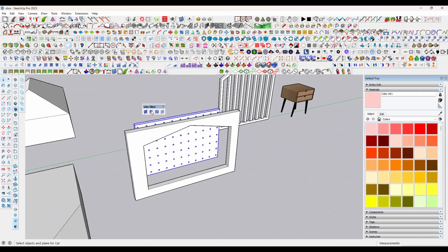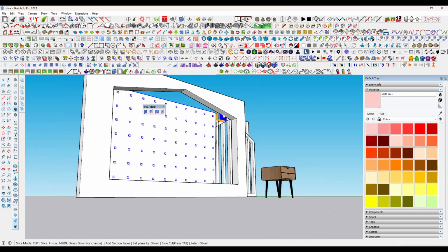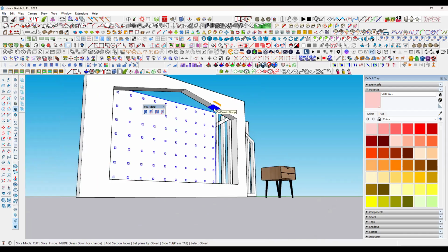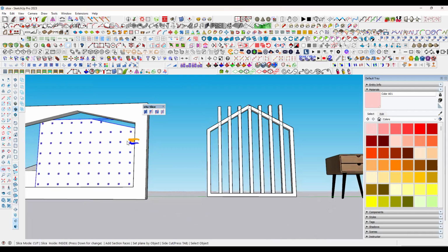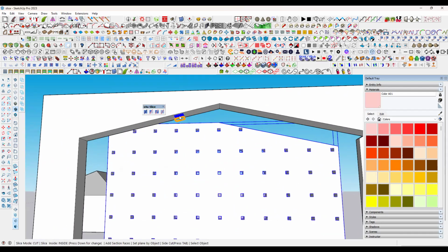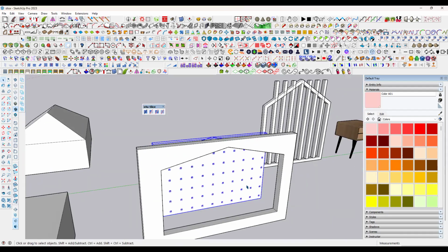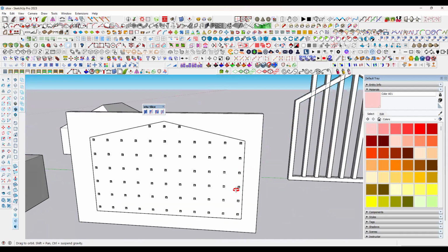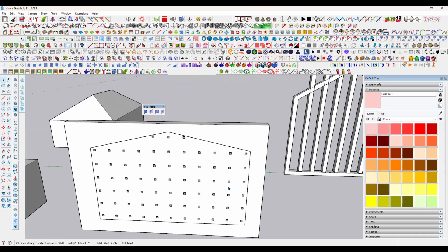But this time, whenever you are making the slicing, you want to take a face as the reference. Select plane by object. Now see, I'm selecting the upper surface in this one. See, it is making the slicing this side, but I don't want the opposite side now. Tap, click that. See, it is making a section directly here. Okay, now see, the slicing. Now I can take this one, I can keep it here easily. Without this one, if you want to do this, it will take a lot of time.